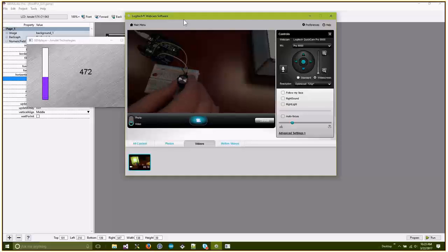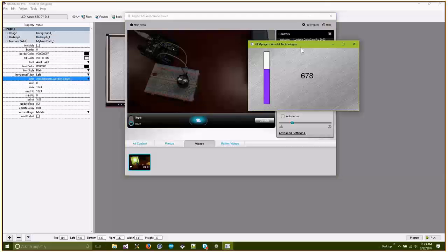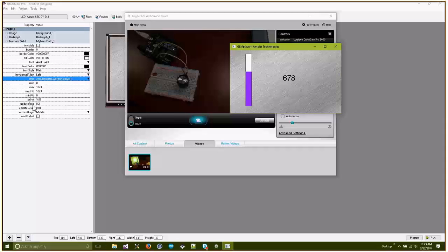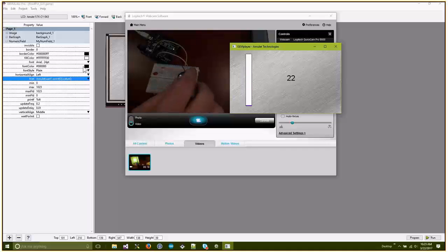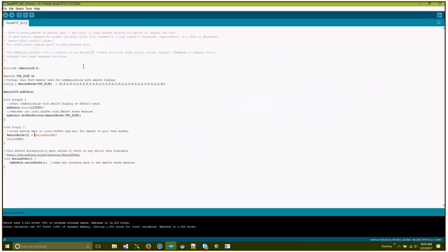So in this example, we are polling at an update frequency of 0.2 seconds. So every 200 milliseconds, 5 times a second, we're asking the Arduino for the current sensor data. We could ask it a lot faster than that, but it might not be ready. Back to the Arduino code, what we've got here is a read and then a delay of 100 milliseconds. We don't really need the delay in there. We could just be reading constantly or going to sleep to use less power.